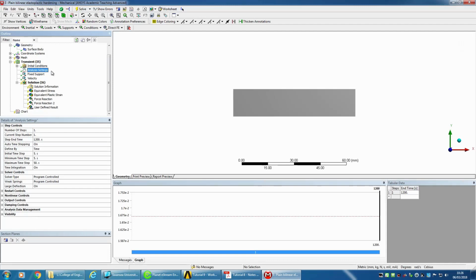With this simulation, we're going to have to reduce the time step. We can run it like that, but it'll just run out. Because it's perfectly plastic, and the way that we set that up, when it goes into the transition between the elastic and the plastic hardening rule, there's quite a sharp transition point in this particular model. ANSYS doesn't like that. It reaches the end of the elastic, and then it suddenly fails. So in order to avoid that, we need to decrease the time step.